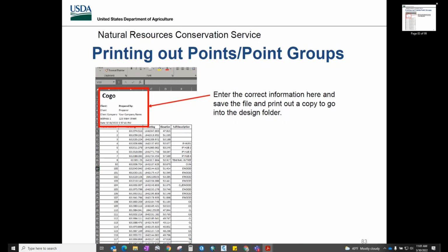Okay. But I mean, you still should go back maybe to your benchmark. You initially set up your, right. I guess it depends on exactly what GPS equipment you're using, but you're usually setting out benchmarks from your initial instrument point where you started. It would still be a good idea once you're done to go back and close on that, just to verify that nothing has drastically changed in the time that you were doing the survey. So I would still suggest doing it that way, as if you were doing a regular one with a total station.